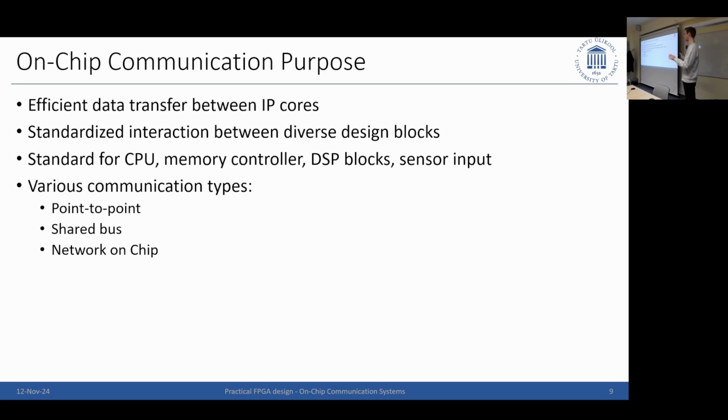You always wrap them in there. Very often, for Xilinx devices literally, you will automatically get a CPU which has an AXI interface, which we're going to come to in a moment. And we always also have a DMA memory controller for DDR3, DDR4, or whatever, which is quite convenient. We have this directly accessible, and we don't have to write this ourselves as an IP core anymore.